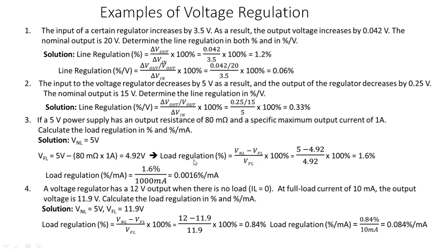The formula for load regulation is VNL minus VFL upon VFL into 100%. We have all these values, VNL and VFL. You can put them in and you will get the answer.